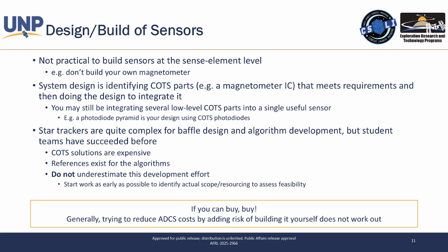And then the second would be, if we're counting on a couple of frames of reference and we're in the eclipse period without a star tracker, I think you mentioned there are some other options, or are there any other options, or do any of those make sense for getting that second frame of reference? Coarse sun sensors are effectively for safety, right? As far as knowing where the bright object is, point your panels and get power generated. That's all they really do.